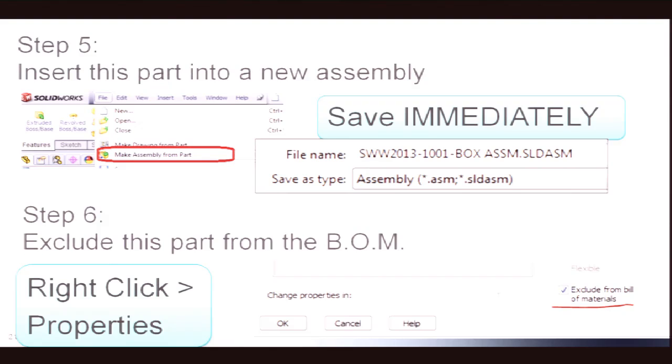And the reason that step is so important is because, especially with virtual components, I don't recommend working with virtual components in this spot, but you know, it's marginal. It's one of those, if I was doing it, I wouldn't do it, but I'm not going to tell somebody like, no, you're doing it wrong. It's marginal, but I wouldn't recommend using virtual parts. But if you are, and you make a series of virtual parts and then you save the assembly, it may have a different name now.